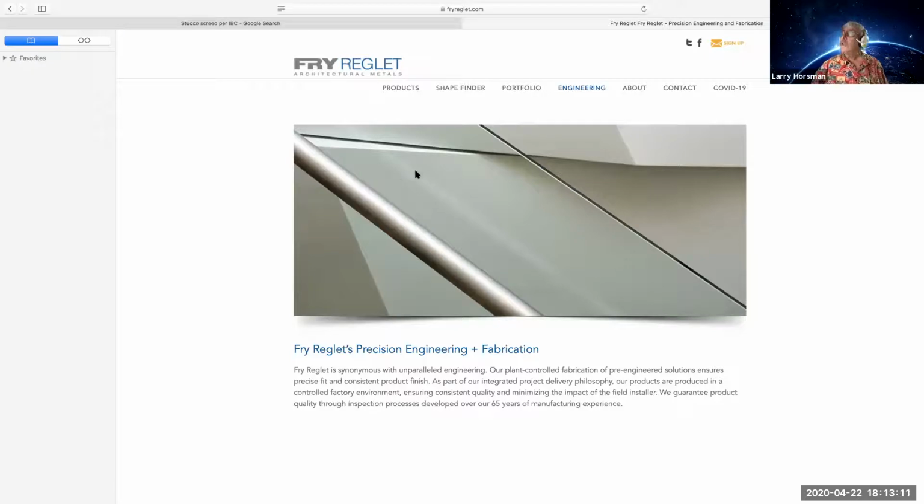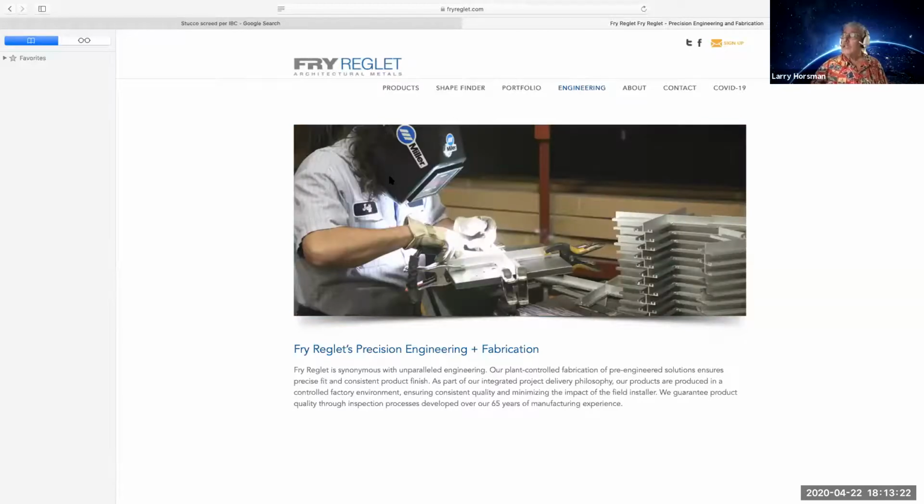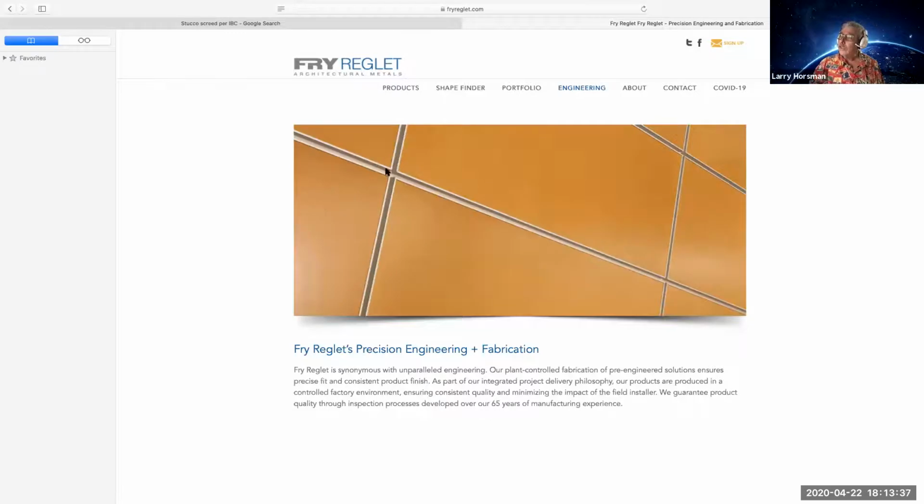Sometimes, rather than having it open on all four sides like this one is, you'll run one of them straight through and the other one will just butt up to the sides. That's the architectural stuff. You need to pay attention to that and look at the specs, because they'll come back to haunt you later where you thought you had it covered. You spent a lot of money and then it turns out you've got things installed not the way the architect wanted or the owner was expecting.